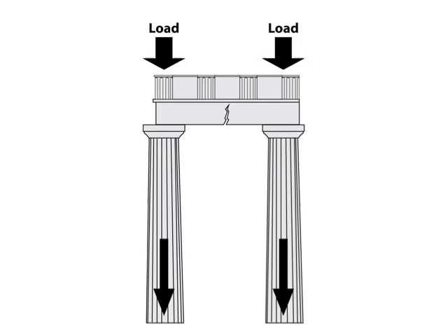So this is a major limitation on the prop and lintel system, particularly if you're building out of stone, is how long or how wide you can have a lintel. There's actually a limitation on this. And so this meant there was a limit on just the inner dimensions that you could span with stone lintels in these ancient temples. Now if you did want to span a greater gap, then you had to use a material that was not stone.